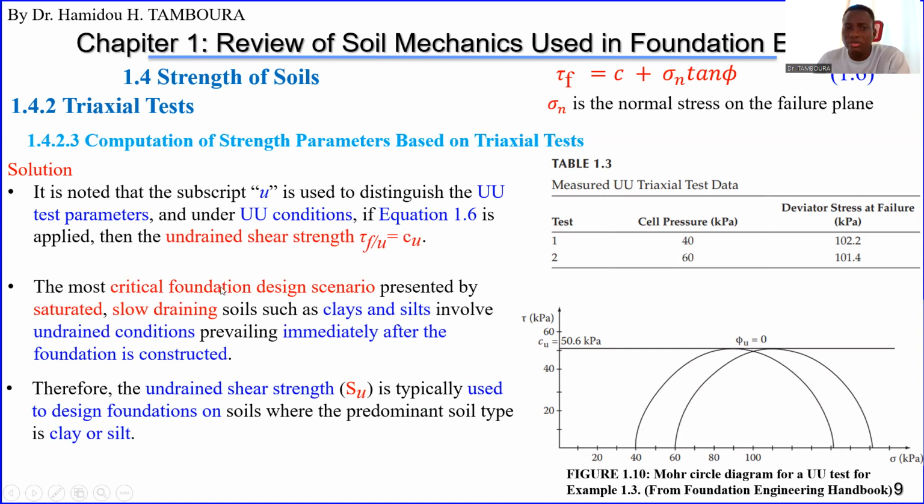So the most critical foundation design scenario presented by saturated, slow draining soil, such as clay and silt, involves undrained condition. This is prevailing immediately after the foundation is constructed.